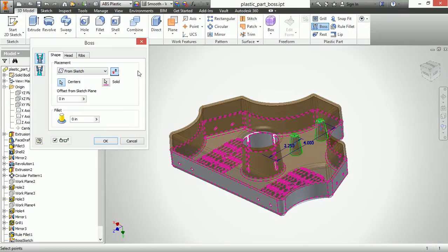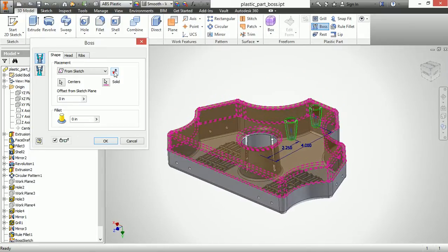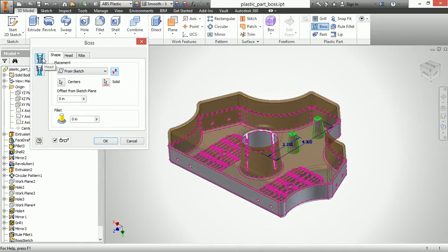Now it is currently building itself into the gray solid, and this is currently the head side. If I wanted to go into the other solid, I would have to choose this solid button here and then pick the other solid and then also reverse the direction to have it go up instead. So here I wanted to choose the gray solid. I'll flip it around so I can build my head side going that way.